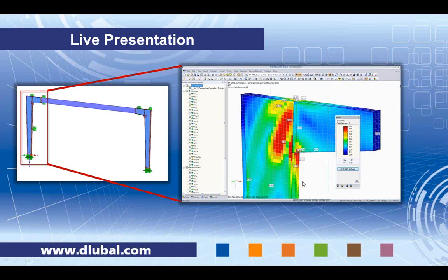If we have not a rectangular plate, or a certain type of supporting of the rectangular plate, or a certain type of stress introduction into the shear or buckling panel, then it is better to do an analysis within a finite element software.